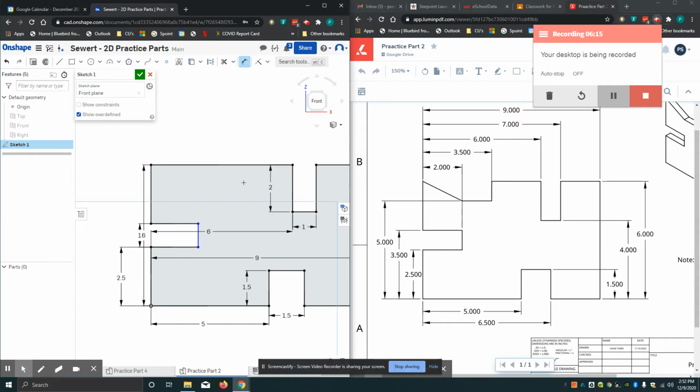And that got that all set up. For some reason, the 2-inch dimension didn't stay, though. So I got to dimension that again. See how this line is blue? That means it's not fully constrained, and I can click on it and change it if I want to. So I'm just going to dimension this by clicking on it here and here and here. There we go. And 2 inches. And I'll hit enter. And now it's fully constrained.